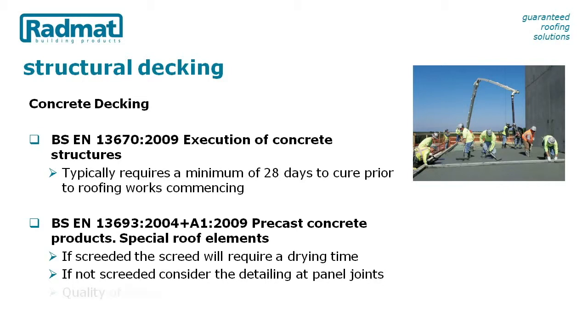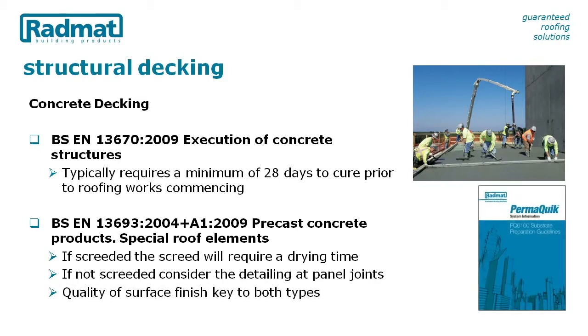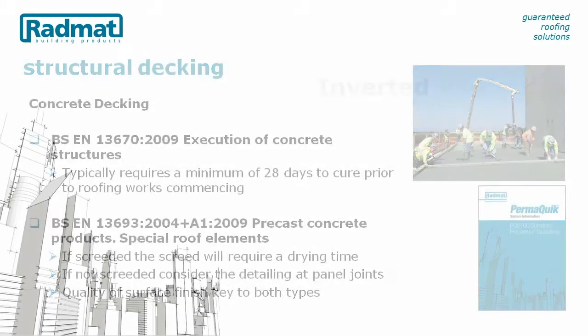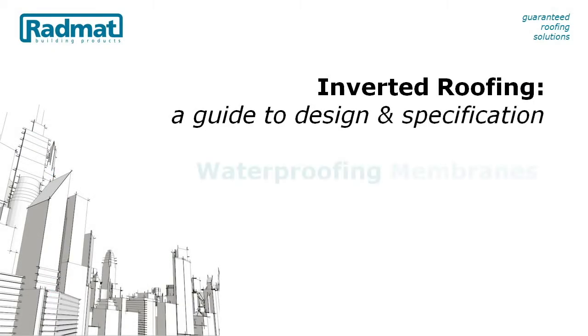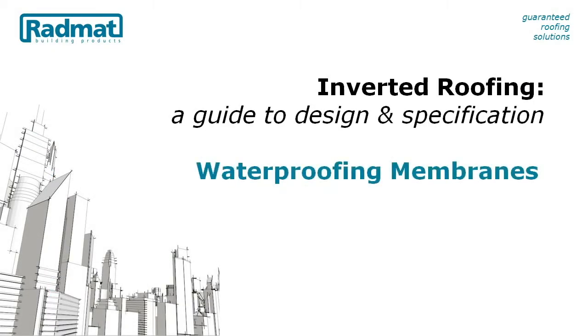Glue laminated timber, GLT, is also used on occasion. Whatever deck you have, it's important that the substrate is correctly prepared by the main contractor, which is why we have produced this guidance document for specifiers and contractors. Next in the construction comes the waterproofing membrane, and we will look at the main generic types used in inverted